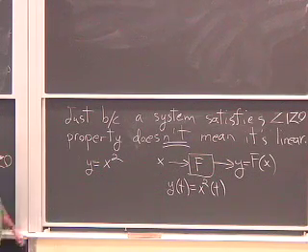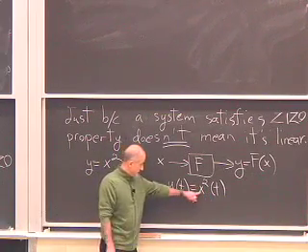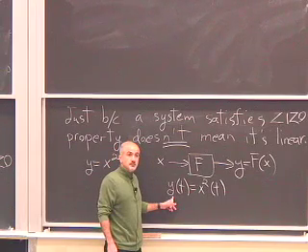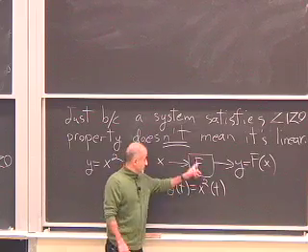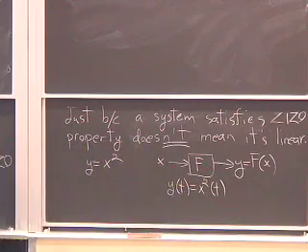Such a system clearly is not linear, because you can easily show that if you scale the input signal by alpha, the output scales by alpha squared. So this is not a linear system. And yet, a zero input signal will produce a zero output signal. And that's why it's important for you to realize that this arrow does not hold.